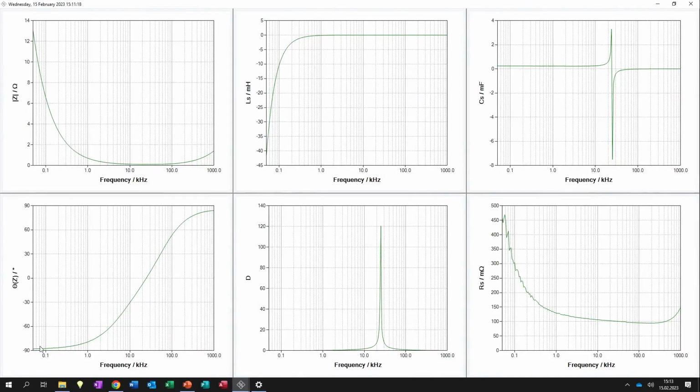So we can see here that the impedance angle increases. It goes from -90, which is a capacitive behavior, until 90, which is an inductive behavior, and the same with the magnitude. This resembles the graph that was shown before in the webinar. Also, we can see here that this transition point is more or less at 25 kilohertz.